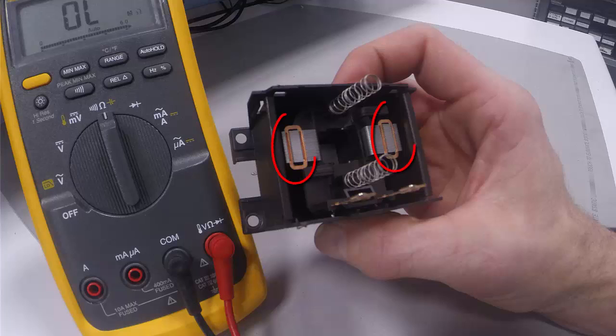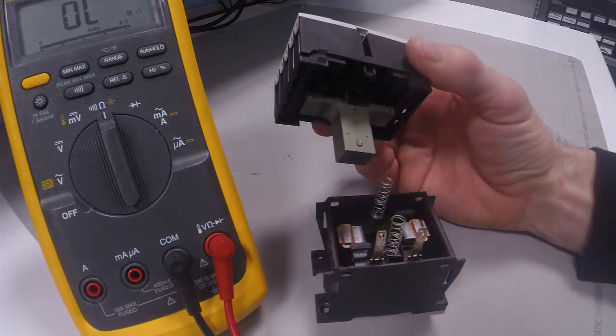Notice the shading ring. The coil is meant to be energized by 120 volts AC. The inductively linked shade ring keeps the armature engaged during zero crossing of the AC waveform and keeps audible hum to a minimum. The top portion contains the contacts, the contact carrier, and the armature. When de-energized, the return springs push the armature away. When energized, the coil pulls the armature into it and the associated contacts change states.